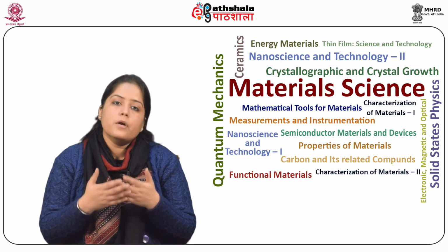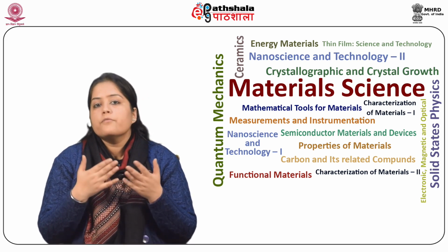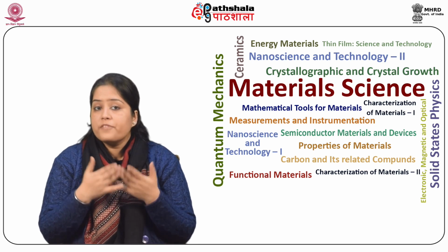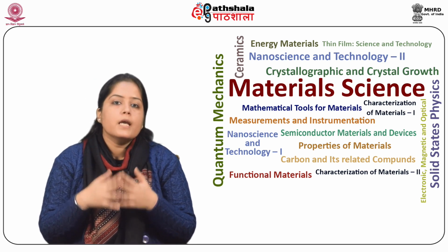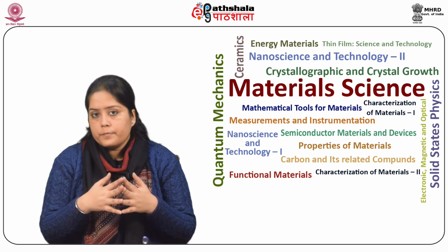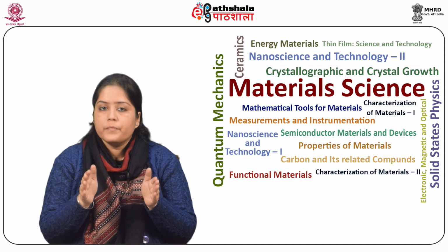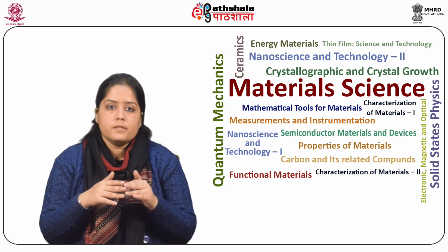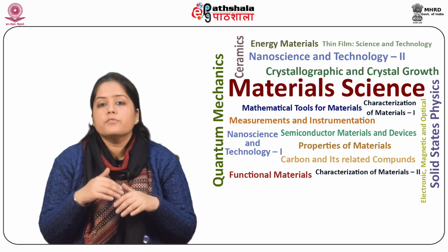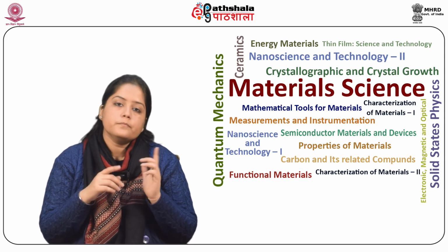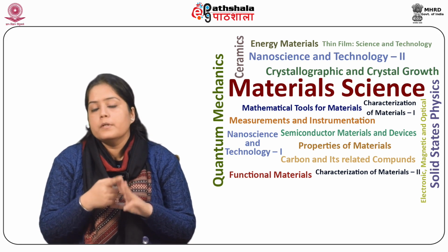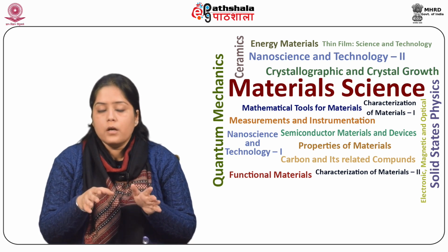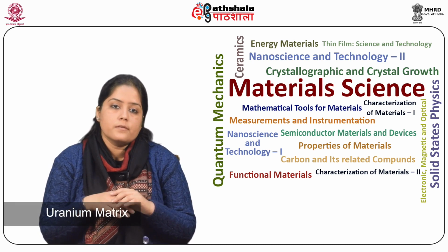Further, the uranium alloys based on fissium, UFS or UFZ, that is fissium, are being used in LMFBRs. Uranium fissium is produced while reprocessing of spent fuels, in which an amount of the fission products like molybdenum, niobium, zirconium, rhodium, and ruthenium, etc., are left in the uranium matrix.